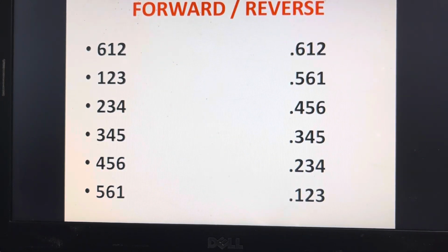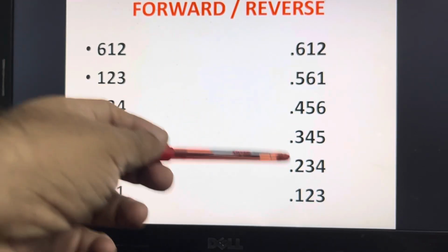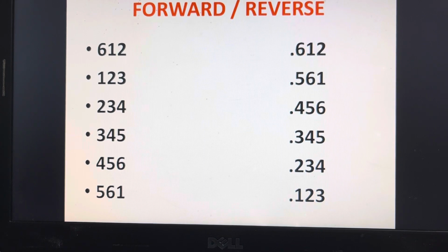The switching sequence of the inverter is 612, 123, 234, 345, 456, 561, and null state is triggering all the upper devices, say 135 or 246. So in null state 0 voltage is applied. If you want to reverse the sequence, after 612 you get 561, then 456 and so on. So in an electric vehicle, if you select the reverse option, the switching pulse sequence is reversed and direction of rotation of the motor gets reversed.